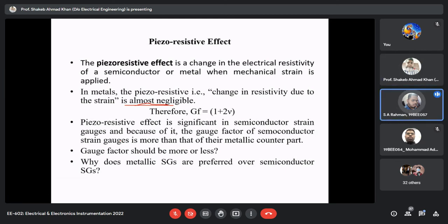That's all we know now. Anyway, not the correct answer. Somebody else was telling something. Sir, gauge factor in a strain gauge must be high, because for good sensitivity it needs to be higher. Sensitivity will be high. Yes, you're correct. So that's what I want to know.